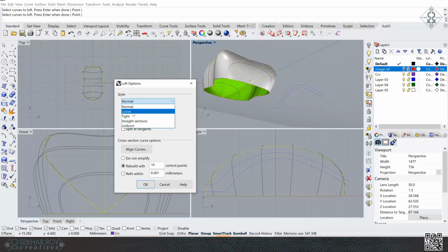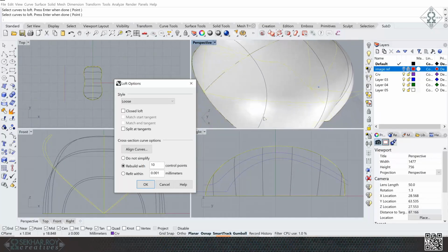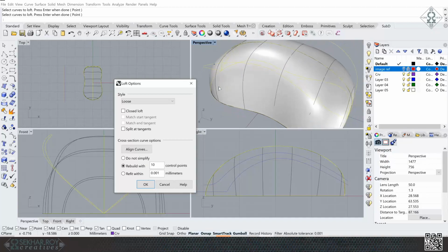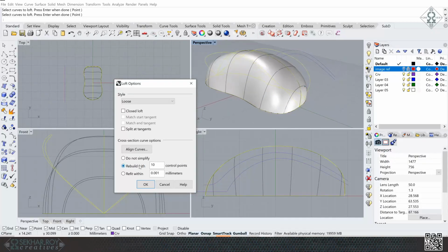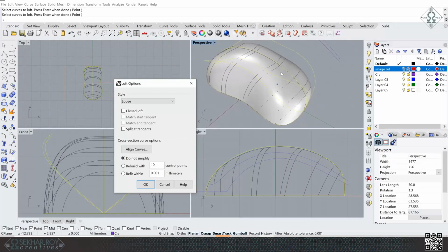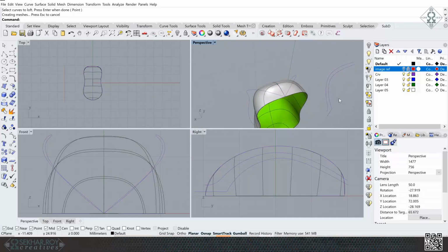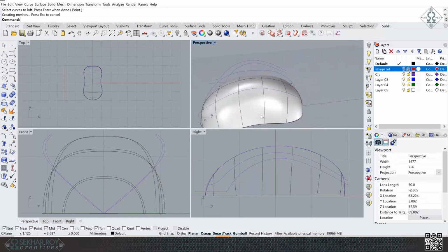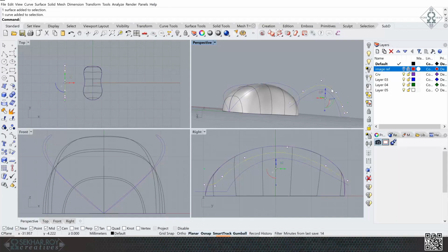So make sure of that. I'm going to go loose, so it makes it a loose surface. The ends also look nice and smooth. Once we have the surface that we want, look and see that it makes me a wider surface on top. Rebuild option is active. Without this, it was giving me iso curves not so well distributed. I'm going to make this rebuild and click OK to accept. Okay, the bottom is still open. We'll close that later. So once we have this, I'm going to select my shapes here.